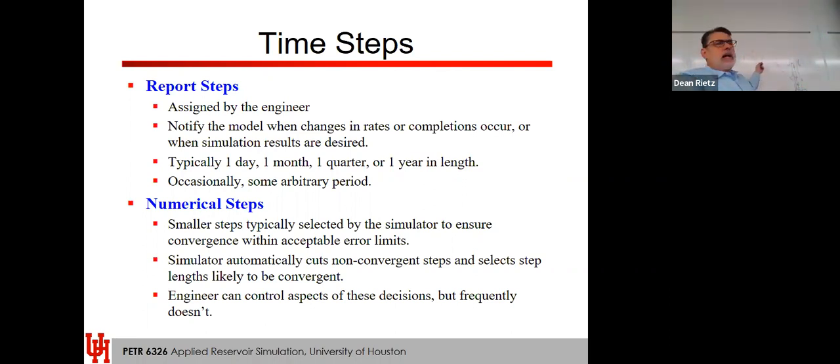And I just said 16 days, right? If that didn't do anything, change it to 5 days and then see. But you could also use this with the plot of time step and you could kind of balance it. If most of your model is running at 30 days and there's only a few places that are a problem, well, you could put multiple T-step keywords in there. You could say, okay, I want you to just take daily time steps until you get through that crunch and you're back to normal again. So it's a real easy thing to do. You don't have to change anything with the model except that one little time step.